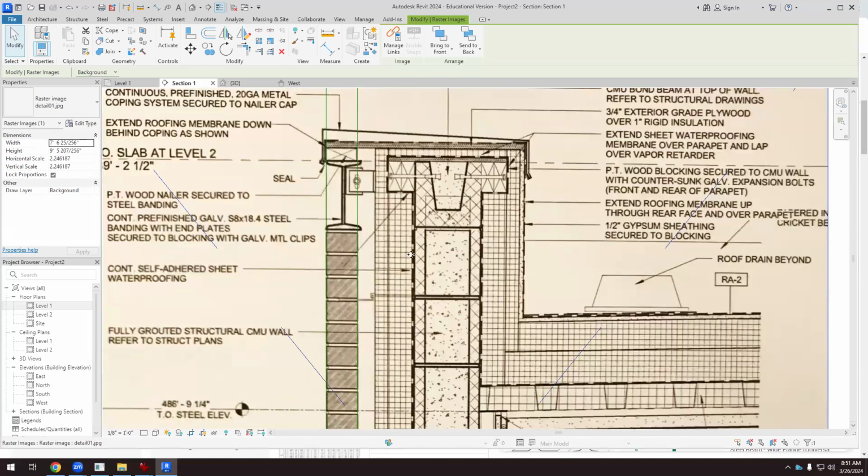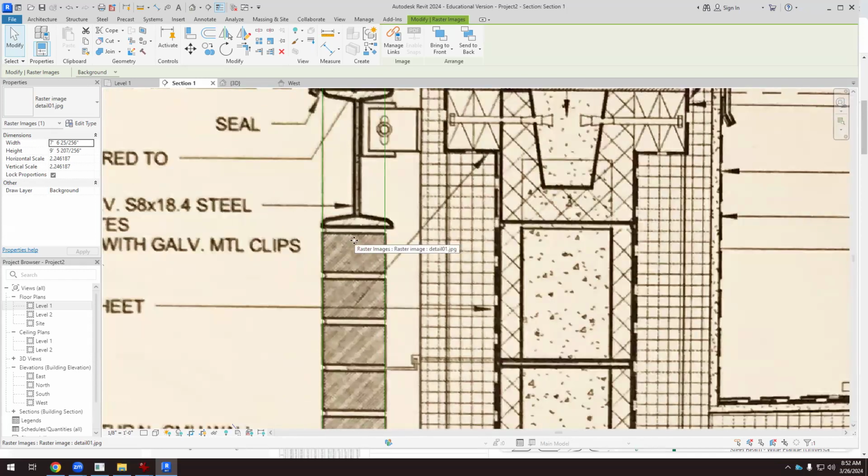So now I want to measure this. I know concrete masonry units are 8 inches, 10 inches, 12, 6, I think it's 4, 6, 8, 10, 12. I don't know if there's a 14. But again, the brick is 4 inches, but it's not 4, it's 3 inches and 5/8. So probably the concrete masonry unit is not 8 inches, it will be 7 inches and whatever.